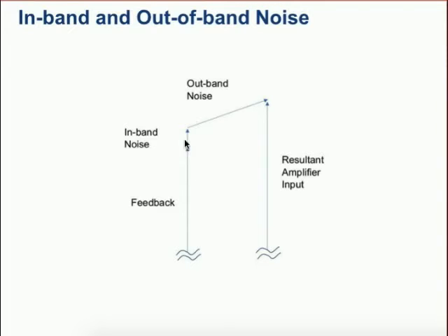So it is this in-band noise that is amplified up to limit level in a normal practical oscillator, and the bandwidth of this noise is actually important to the derivation of the Leeson equation. That derivation, in fact the whole Leeson equation, relies on this being a specific bandwidth related to other things in the system.